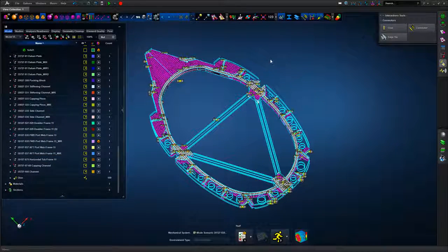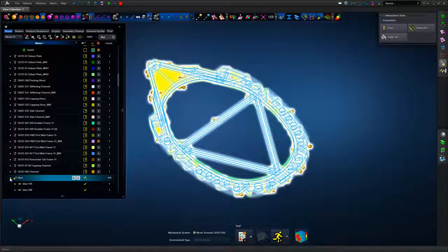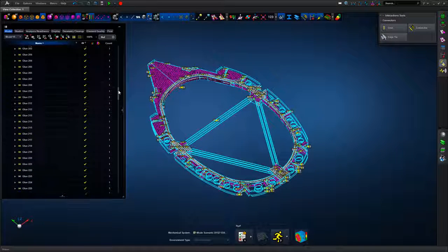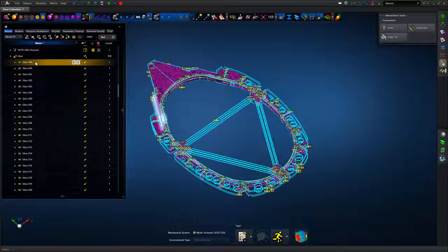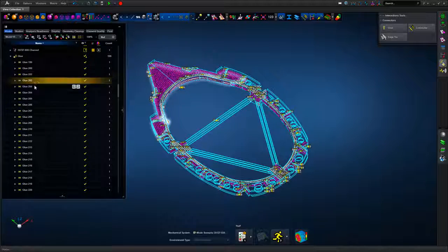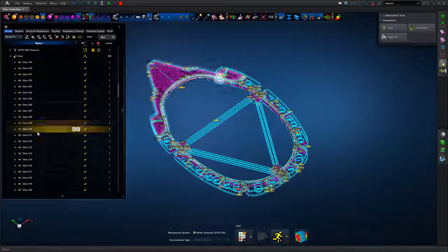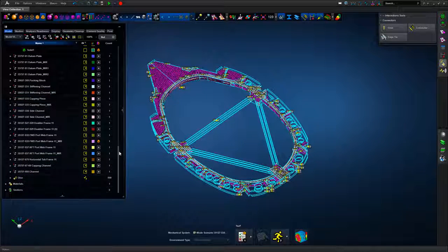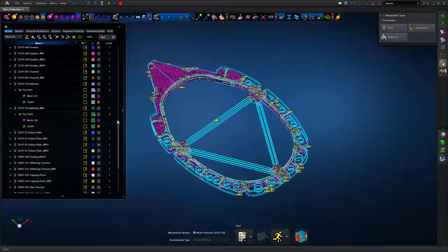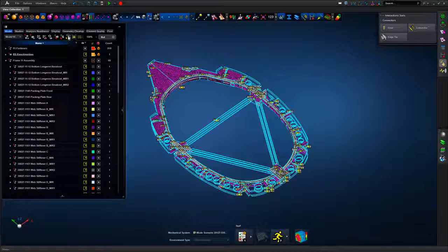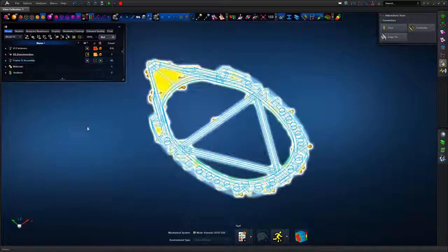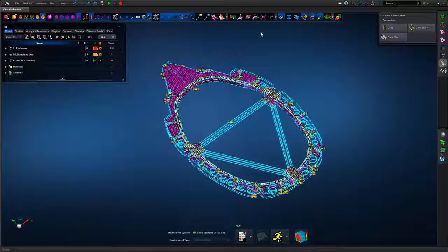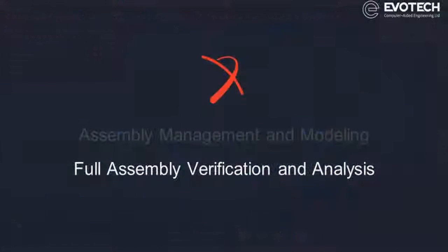Once we've got those controlled, we can view each glue pair, a connection between two parts or sub-assemblies, and cycle through the definition within the model browser tree. One thing I'd say is that the glue technology does consider the extreme fibre surfaces of each shell element. So if you've got two solids butting which are represented with shells, it will glue them together correctly.